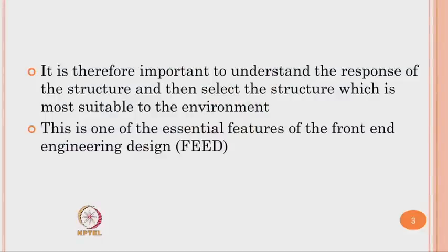This is one of the essential features of what we call, in the offshore domain, front end engineering design. Front end engineering design focuses on selection of a geometric form, the selected form's viability, its stability and its assurance of yielding a return without failure when the platform is intended to be put to specific critical environmental loads.